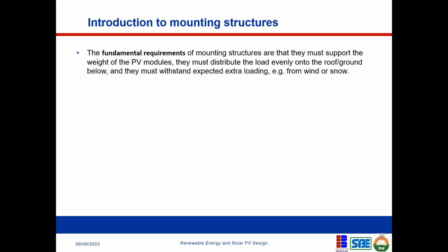You see some buildings where you have to place panels on all the roof surfaces. When you combine the weight of all those solar panels, it is significant. The roofing structure may not even be strong enough to support the weight of the panels. So it is important to examine that before you go ahead and mount your solar panel.